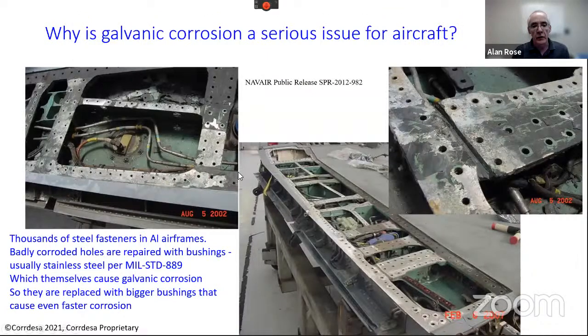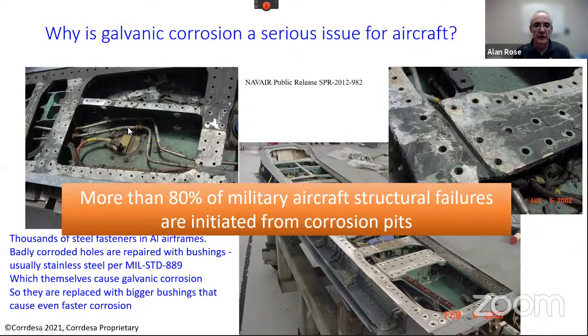All right then, so there was an F-18 there on deck, and if you were to open up the panel on the F-18, carbon composite panels, underneath there you have this aluminum structure and a lot of interaction, very nasty. All these steel fasteners interact with the aluminum airframe and the carbon fiber composite and cause corrosion. And this is important.